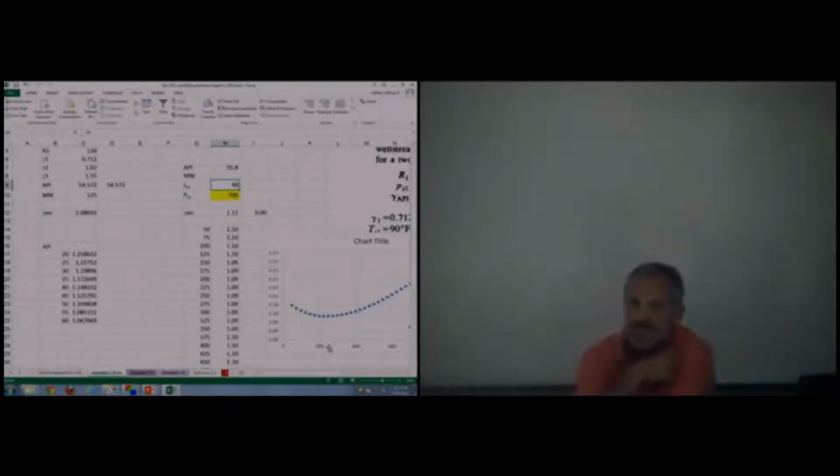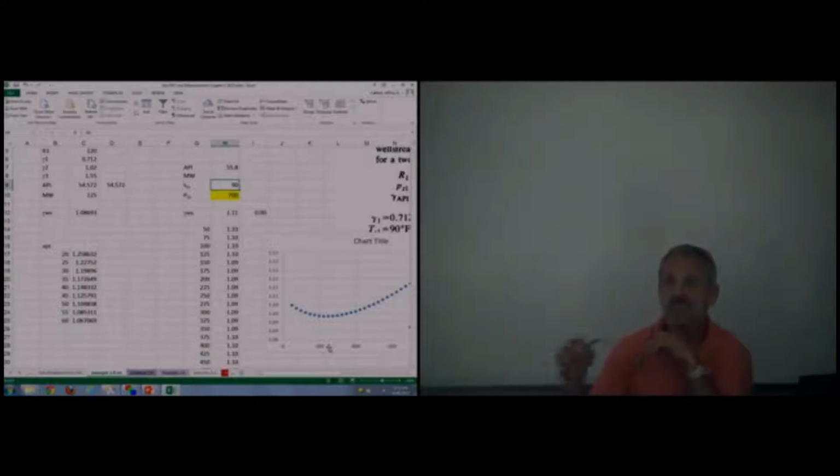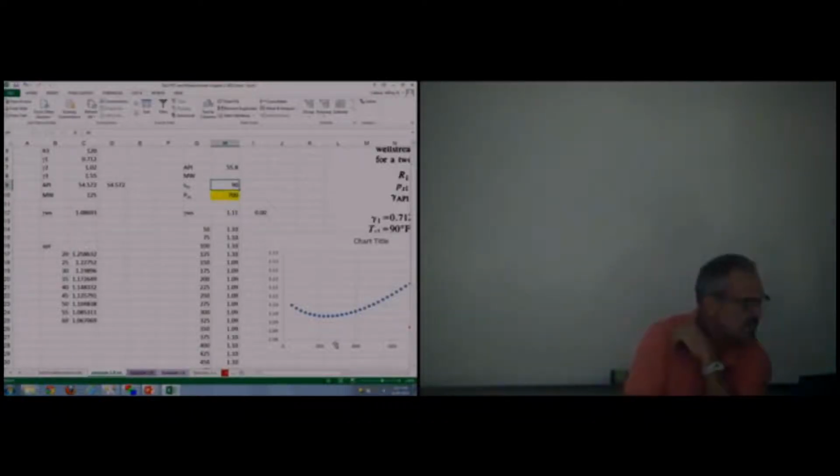Okay, so what about the situation where you say you're going to give us that information, the first one, where the gas gravity is 1.086. What about if we run our iteration and we could get a lower value as compared to the one you gave us? Should we go for the pressure for that lower value? You understand?